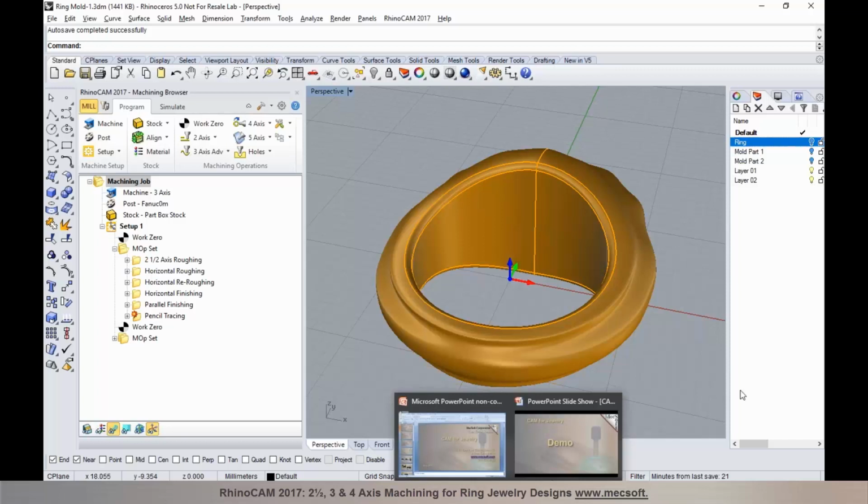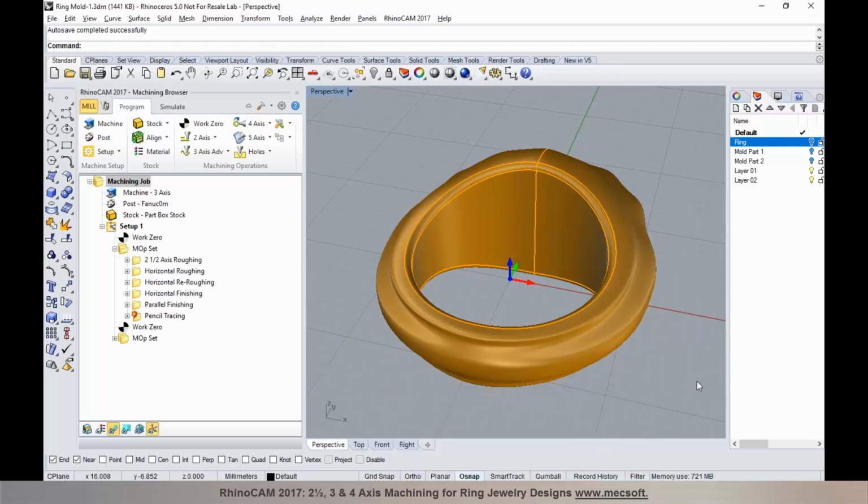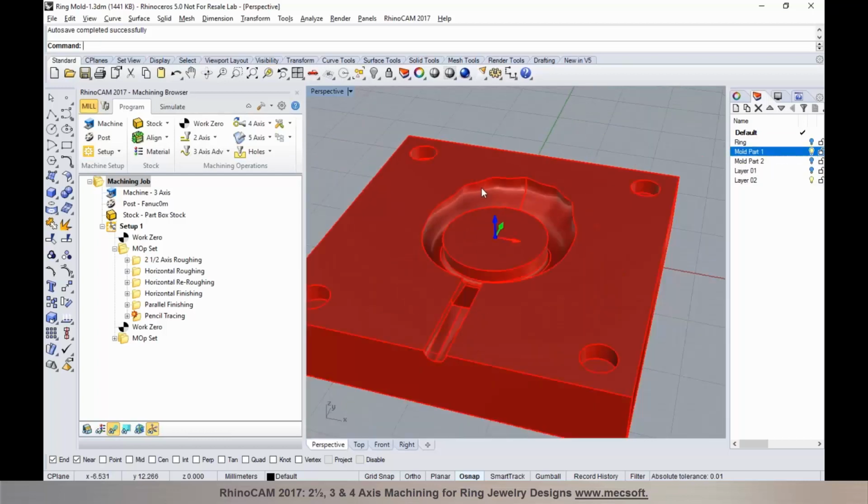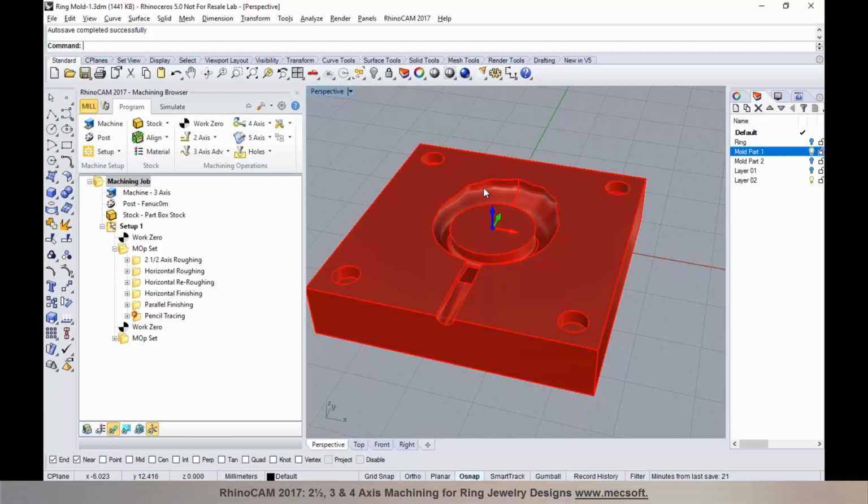Before that, I just want to interject a little bit here. Another word on process. So what they just did or showed us was the master mold for maybe a wax model. So you're creating an injection mold that you would create a wax model that we later take to an investment casting process. So this is the first process that he showed.